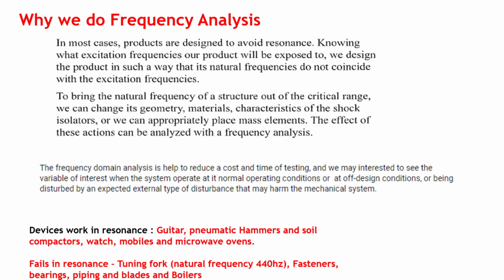A very important thing is why we need to do the frequency analysis. The products which we design should not have resonant frequencies. To avoid resonance, we use the frequency analysis. It helps us to know the excitation frequencies of our product, which will be exposed to environmental conditions.